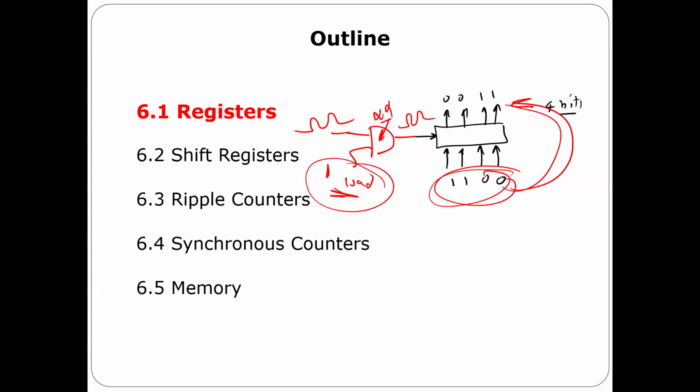What happens here is because of the delay of this AND gate, for example, if you have a rising edge, all of the system has 1 clock, as I told you before. So all of us are going to act at the same time, except this one will be delayed a little bit, some nanoseconds or microseconds. If it's not a problem for you, yes, you can make it this way. But keep in mind, you are going to lose some synchronization here. But I'm not going to do it this way.